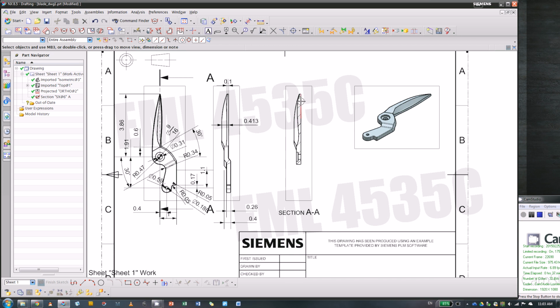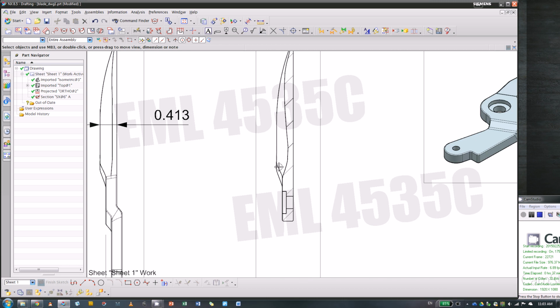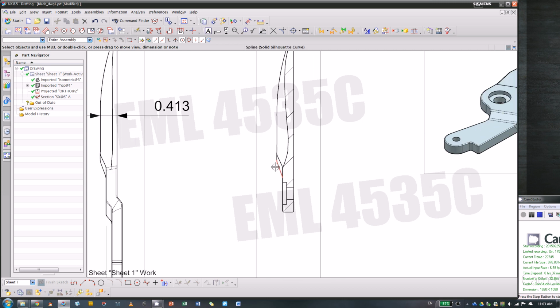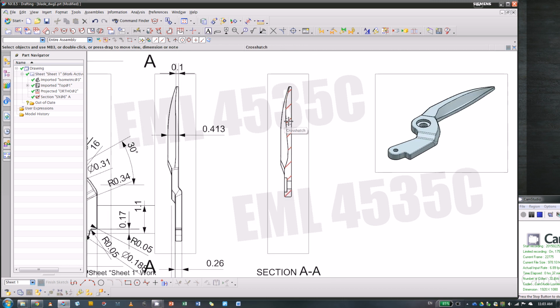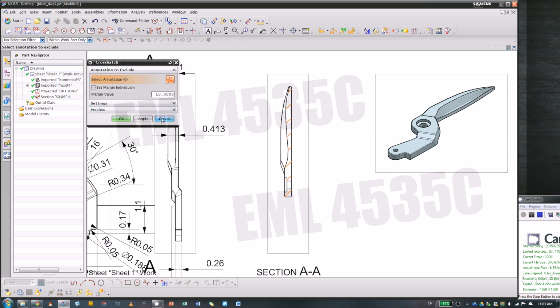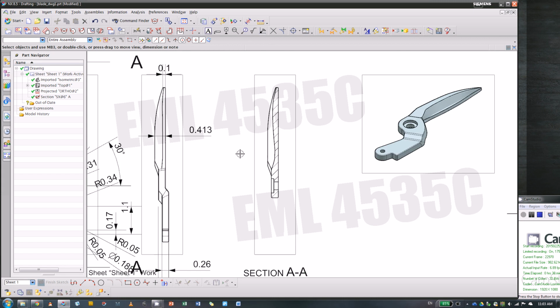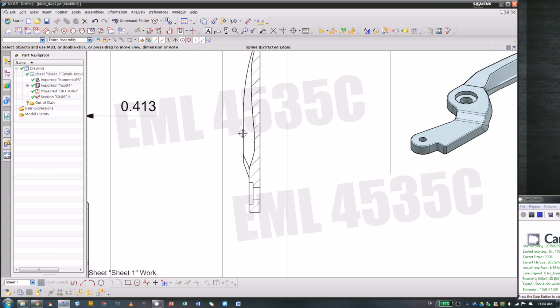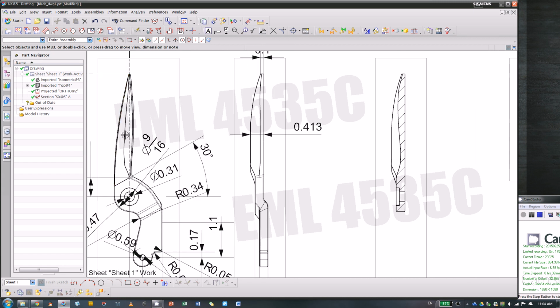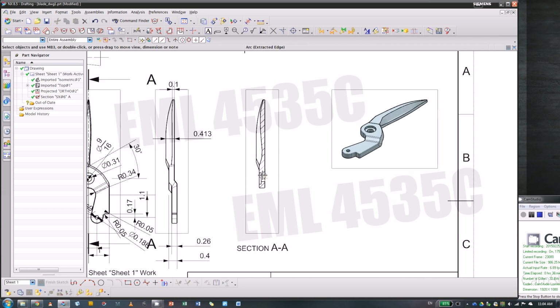What's next is, sometimes you can see the background of this cutting, the area with hatch lines. You can double click, and I think you can change the margin. Apply. Will that be smaller? I think it's this one, distance 0.1. There's a lot of things you can fine tune in the display, and this line here is actually on the back of your cutting as a cross section. So sometimes you don't want to see them.